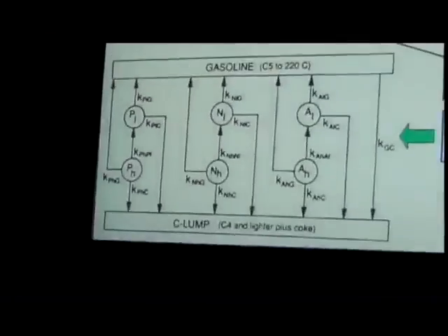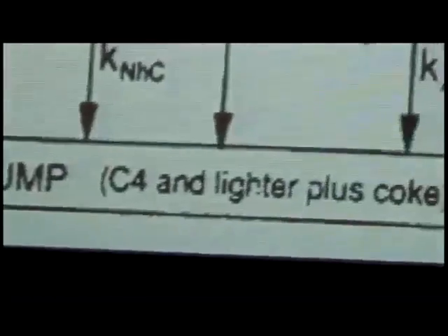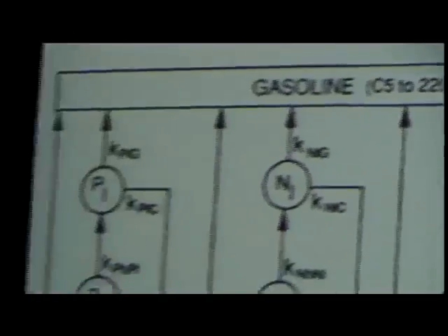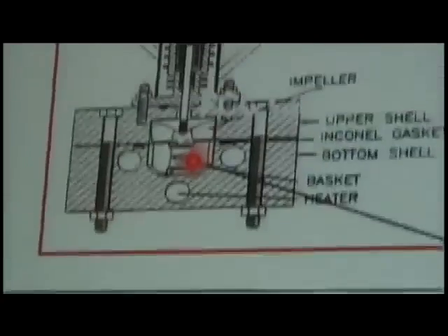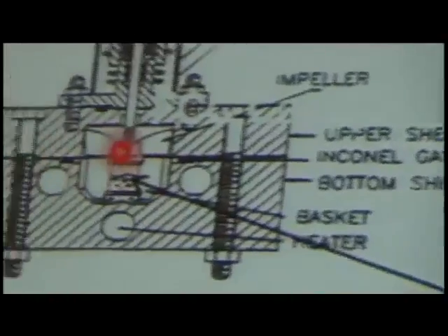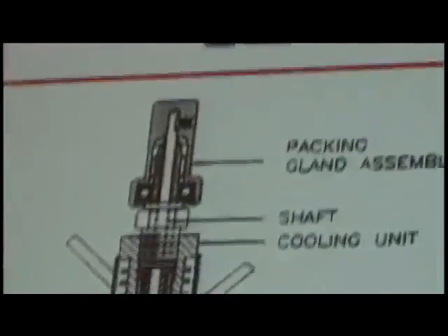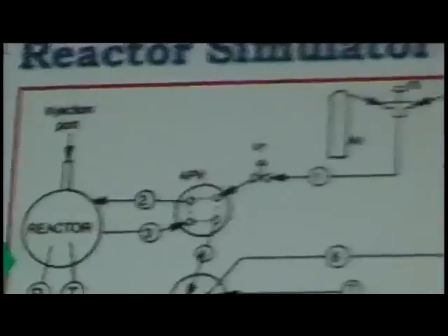It leverages the knowledge from the Berty reactor in the sense that you can use a catalyst powder, but that powder is maintained in a little chamber here, so the powder is maintained in a back mixing type of environment. By changing the feed composition, one could cover a very large range of gas compositions that you might encounter in a typical riser type of system.